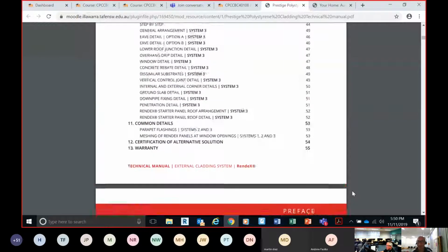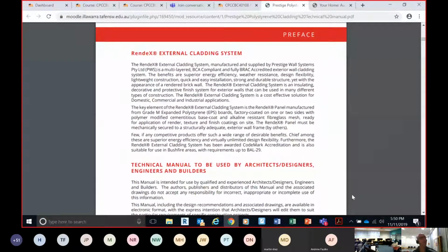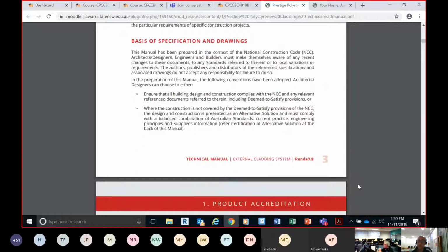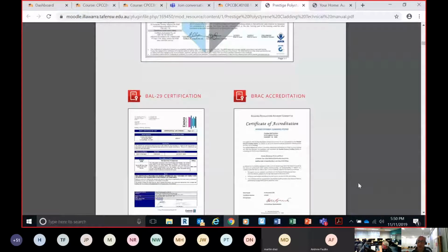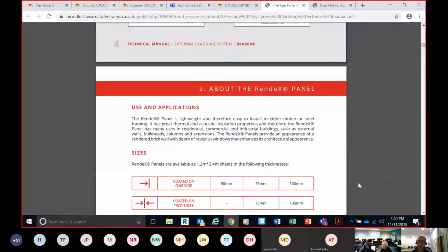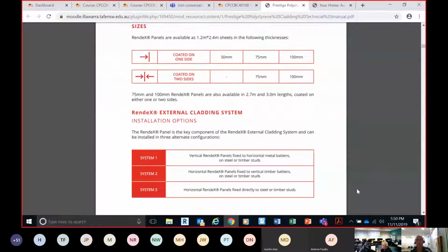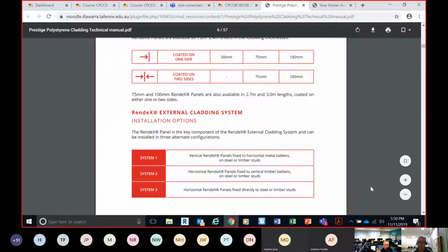And we ended up cladding the outside. So we were using 3-meter panels, 75 mil thick, 3 meters high, 900 wide, Hebel, which nearly killed me because each panel weighed just under 100 kilos. So we did all the lower walls with that. But this pool house pump house was a real contemporary design. It had a flat roof and it had a 900 fascia above the Hebel panel.